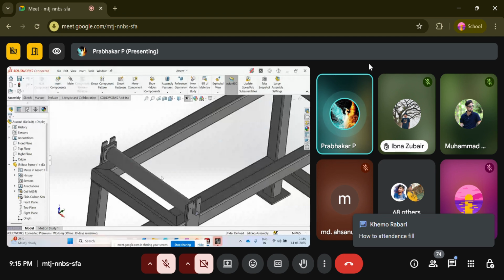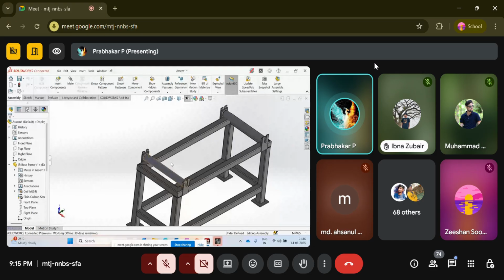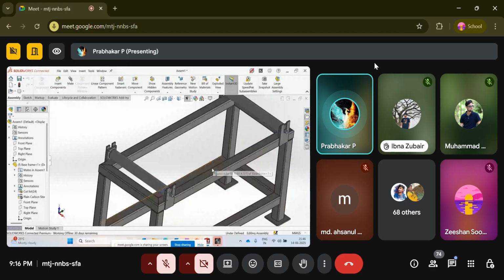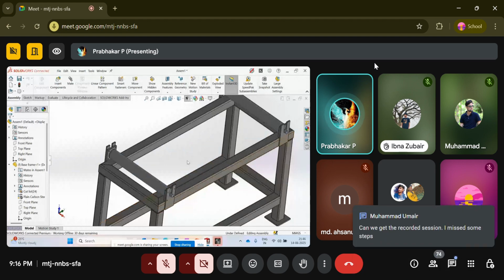When the punch has worked for some number of components, like 10,000 or 20,000 components, it will be resharpened and reused. So that time the inside surface also requires hardness, and we will go for full hardening. So usually the mild steel material, or the low carbon steel material, or plain carbon steel material, will not be hardened itself. The bearing will be of case hardened material, which is medium carbon steel. Usually the gears will be of medium carbon steel.